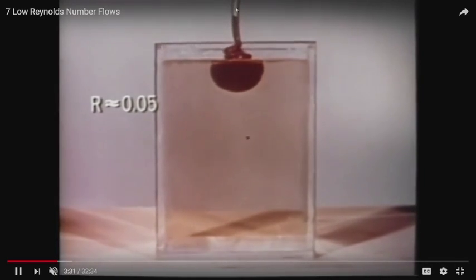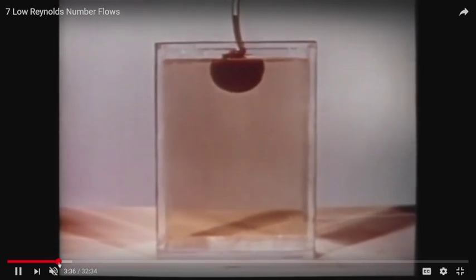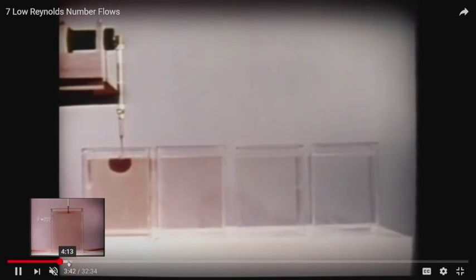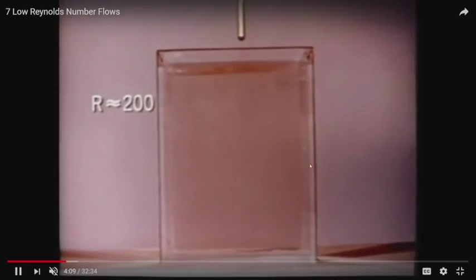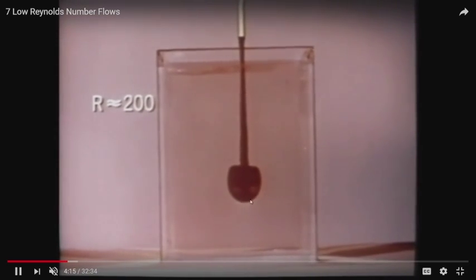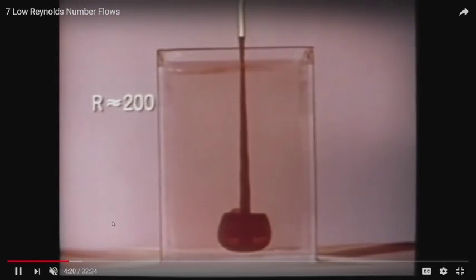The Reynolds number is the Reynolds number of the jet up here. And so, moving right along here, you have a Reynolds number of 10. And the jet comes in at 10 Reynolds number, and you can see that, again, it's fairly poorly mixed. And this is a Reynolds number of 200, and again, a fairly unmixed system. You're still under laminar flow conditions, and still not very well mixed.